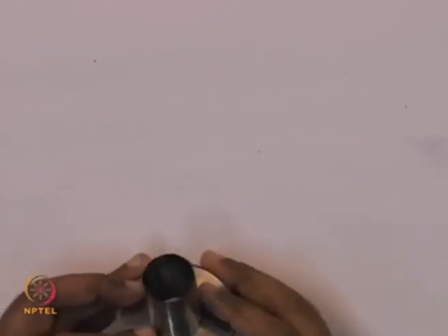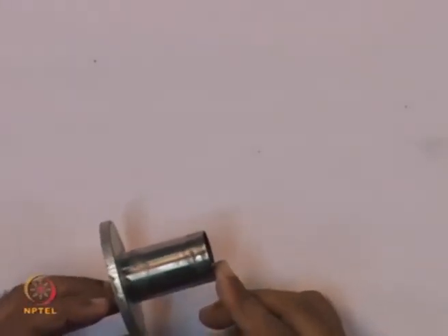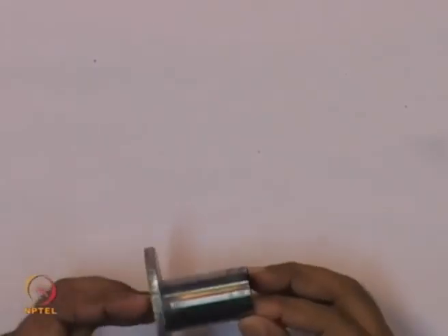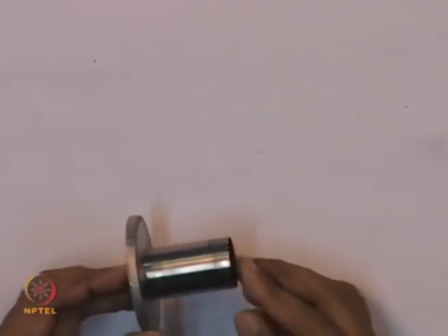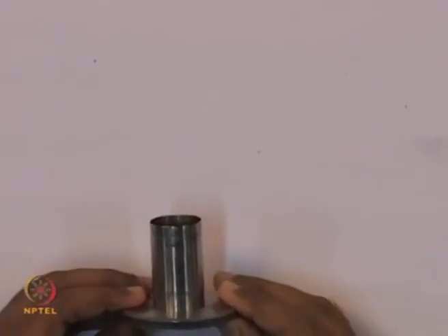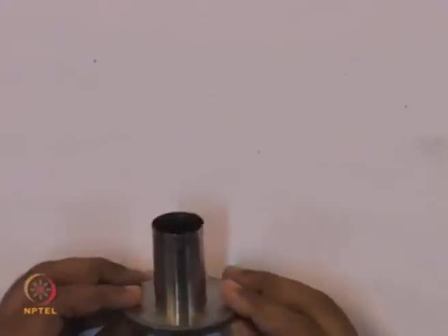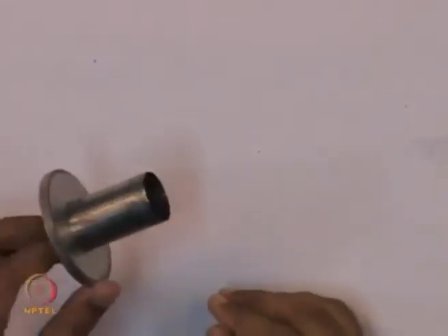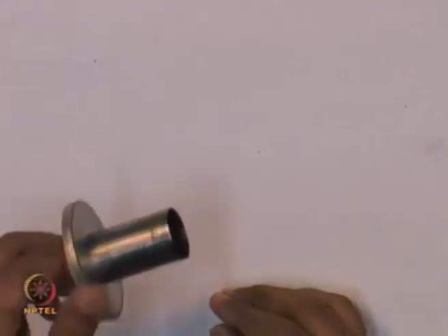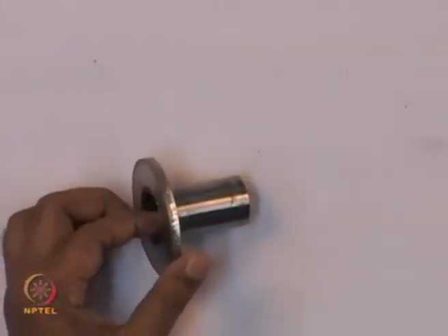It shows that even such a small thickness of a material can stand very high pressure, and in most of the applications, therefore, what we have used is stainless steel. This is SS304 that we use. It stands very high pressure, as high as 30 to 35 bar also. One has to really calculate the hoop stress in this case and then calculate the dimensions, but a thickness of 0.15 to 0.2 millimeter or 0.3 millimeter can stand very high pressure. I just brought this specimen to show you that such a small thin walled tube can stand very high pressure. SS304 is the material which is being used for this particular purpose.